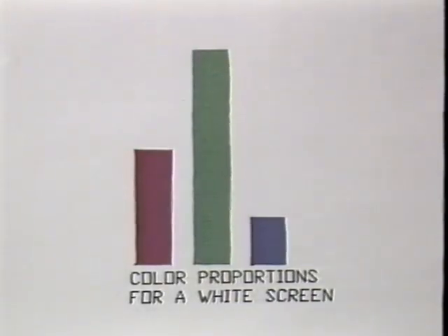Once the cutoff alignment is done, the drive or color temperature adjustment must be made. This procedure varies the drive to each of the three video outputs separately so that all three phosphor colors glow with the same level of brightness. If this adjustment is not done correctly, a supposedly white screen will appear to be somewhat blue, pink, or green. You must sometimes consult with the customer before finalizing this adjustment. What appears to you to be pure white may not look good to him.